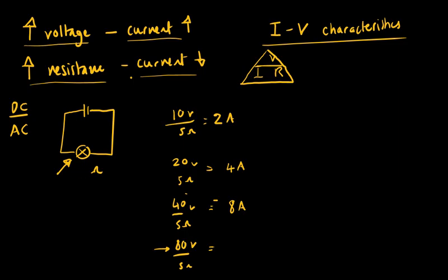So let's say, for example, it pushes the resistance up to not 5 anymore, but to, say, 7 ohms. Now, if I look at the current, I'm going to be doing 80 divided by 7 rather than 80 divided by 5. 80 divided by 7 gives me 11.4 amps.